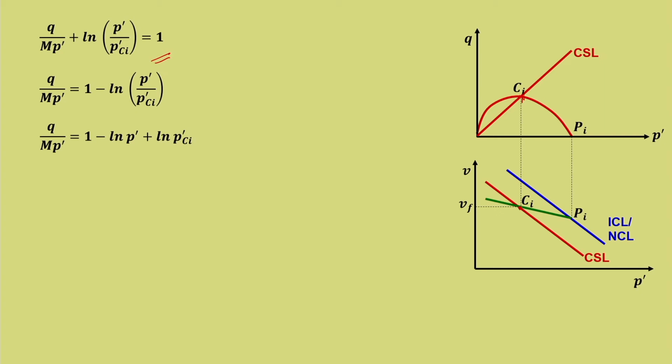Both are the same. If we consider Vf, we understand that it is the failure point and that corresponds to VCS as well. Ci is a point on the critical state line, so designating it as Vf holds good. It also means it is p'f. Now, p'f is the same as p'cs.